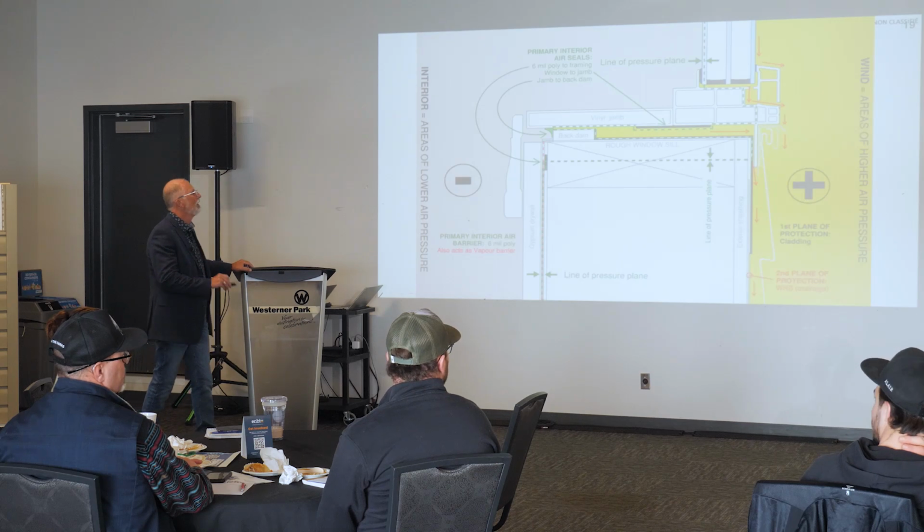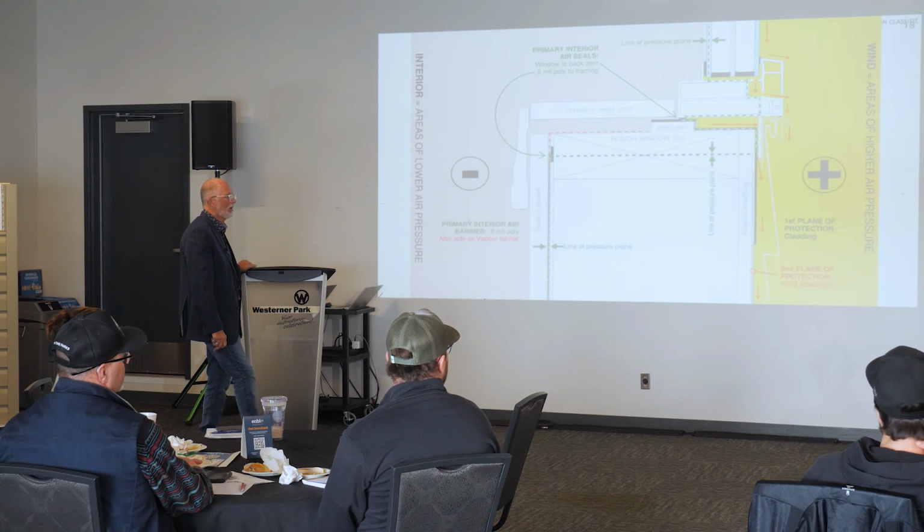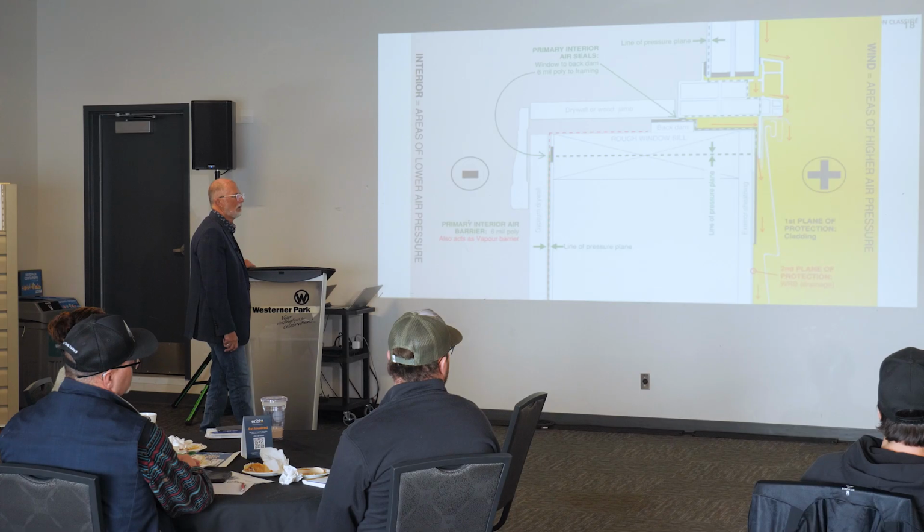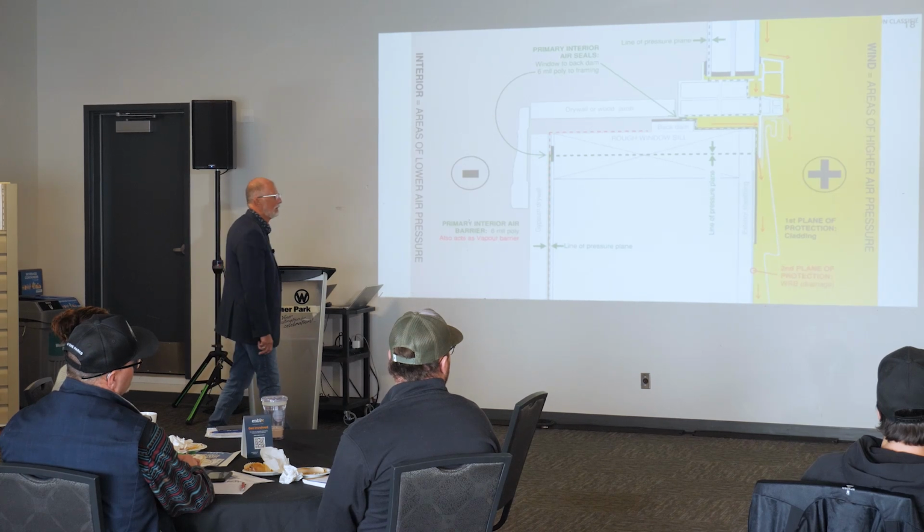Yeah. This is for the installation. I'm looking at there's very little space between the nailing flange and the 2x6. How does the installer or builder maintain that? Most likely in the industry, the nailing fin is used to skewer the window with the rough opening. And at the bottom, if they screw it up, you don't have any room there. Plus, it's such a little space. It's very difficult to maintain that sweet spot.